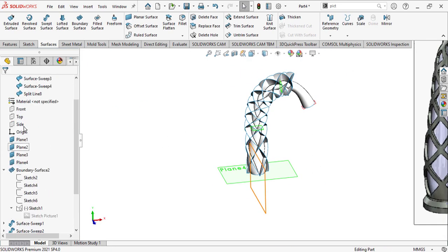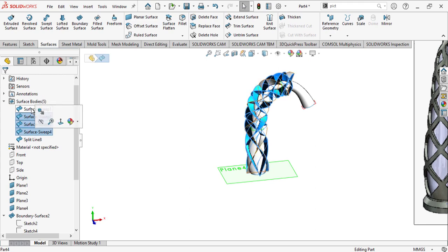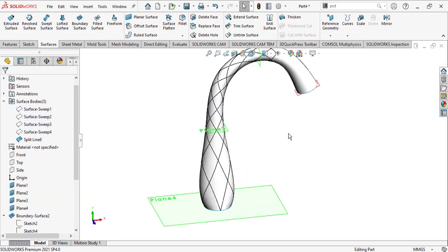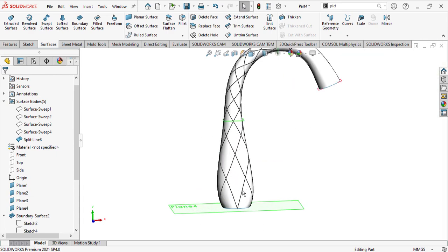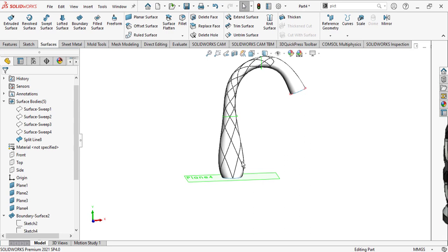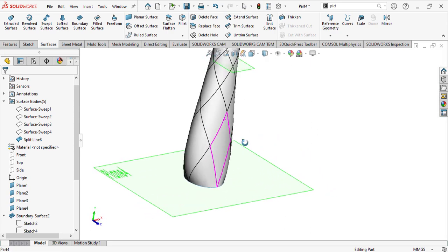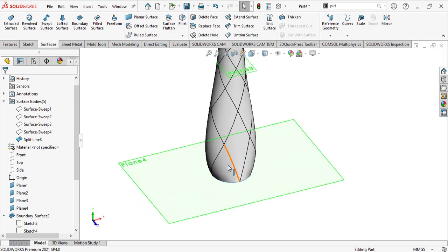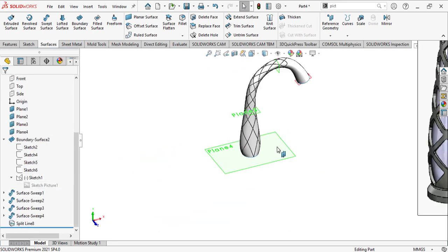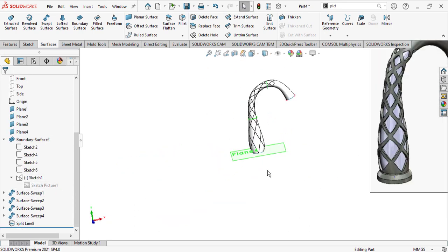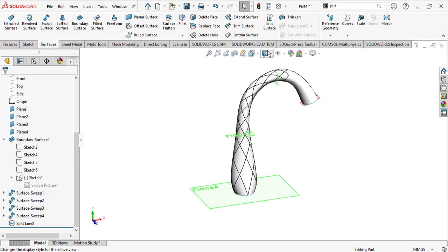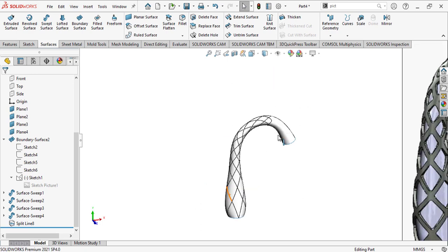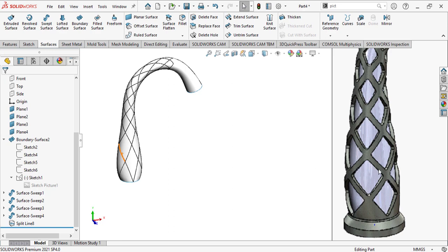After this, hide all of the surface, we don't need, hide it, to get the same pattern of rhombus like this. Also you can minimize this size by minimize your path or profile, but this is okay for us now. We can accept these results. What we need now, let me hide some plans. We need to make thickness, this thickness of diagonal of rhombus.